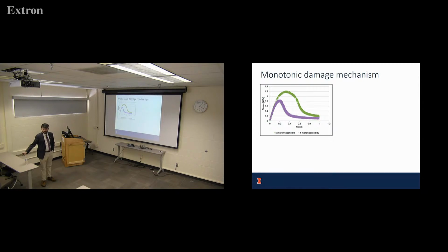And when you did these kinds of tests, did you see any binder flow, like a plateau on that peak? There was one binder. I don't know that it was flow necessarily, but it had almost what you would describe as a plastic response, like a high plasticity, because it got to this point and then it had a pretty drastic change in slope, but it did have much more deformation before it started decreasing from the peak. So the peak was way over here, like at 80%.